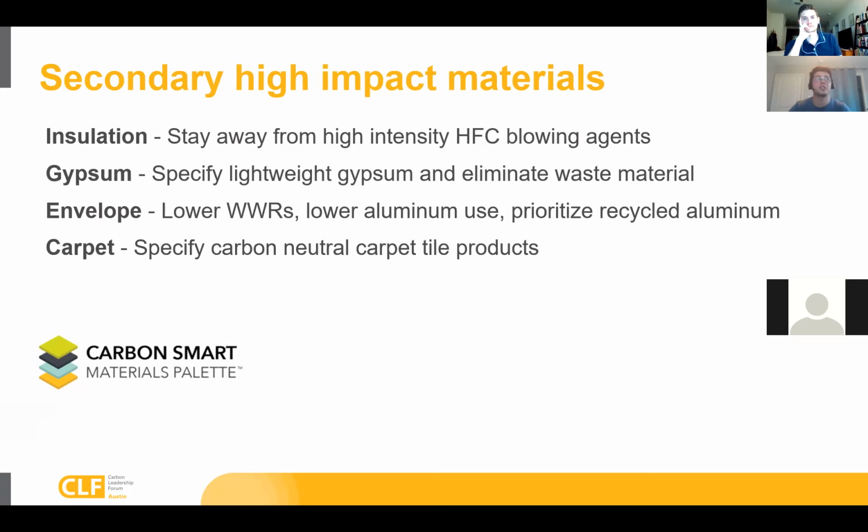And so we've got some secondary materials, looking at insulation, staying away from high intensity HFC blowing agents. So look at material like wood, straw, clay, hemp, cork, sheep's wool. Those naturally sequester carbon. The blown in fiberglass and cellulose insulation have much lower embodied carbon than some rigid insulation or spray foams.